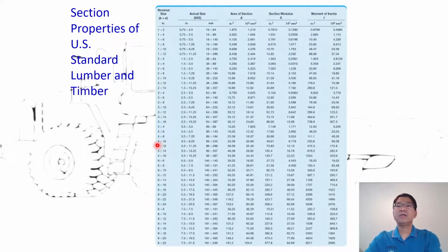Now about the lumber, in the lumber the nominal size and the actual size are not the same, so keep that in mind. For example, if we're talking about the plywood with the thickness, you go to Lowe's or Home Depot, and buy the lumber with the nominal thickness of 1 inch.